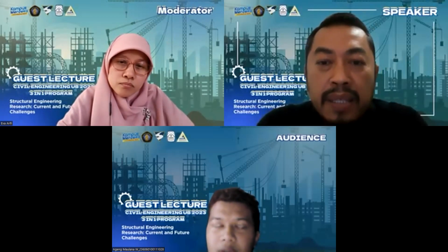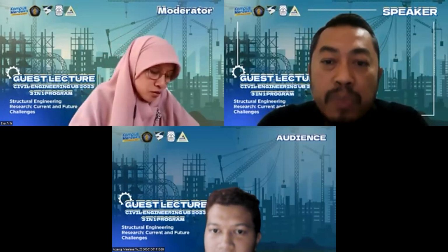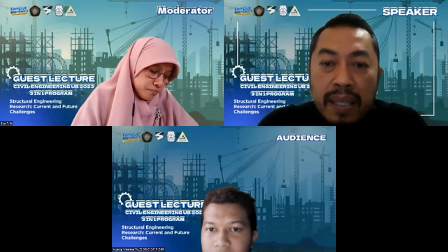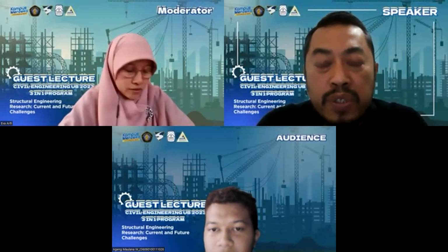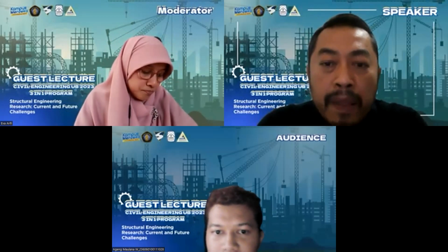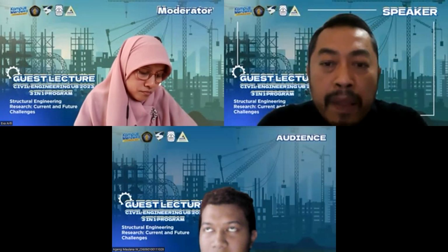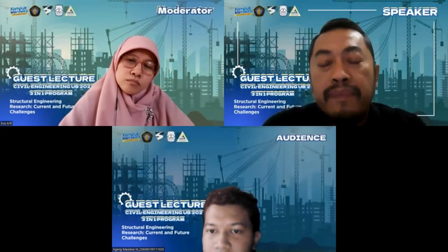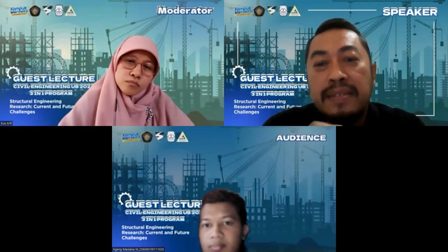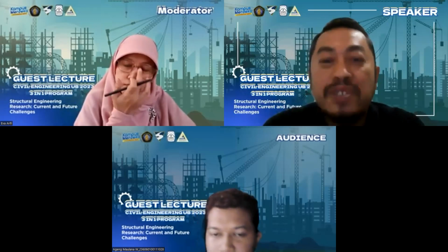Of course, we have very low density because of the residual mortar retained in the natural stone, and we have very high water absorption. So we optimize by reducing water and adding what we call superplasticizers to increase workability. We have different proportions and formulas to design to achieve whichever strength is required.